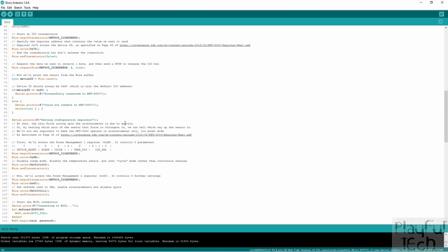Okay, so the data sheet I was looking at here, because we're talking about functions of the chip, relates to the MPU6050, whereas when I was looking at the schematics that showed things like the resistor values that were pulling up the SDA and SCL lines, they related to the GY521 because they're actually the additional components and hardware that's on the board rather than on the chip. So just to explain the difference in case that was confusing.